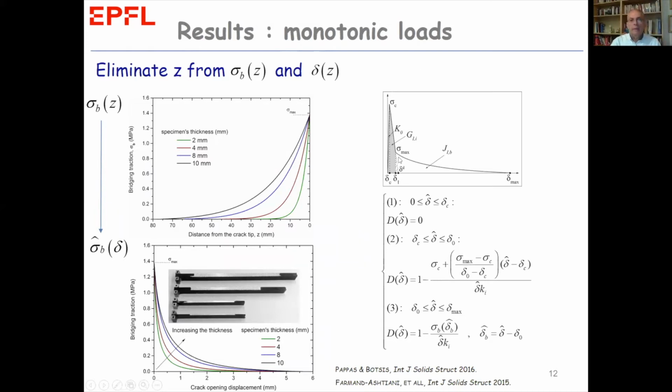Here you see the cohesive zone modeling. The first part here, the gray zone, refers to the standard one, which corresponds to the process zone ahead of the crack tip, and G_I here is the G initiation. And this is what we have calculated using the model I presented to you earlier for a typical case.